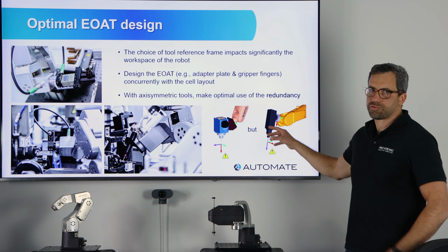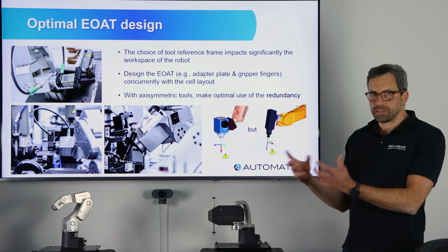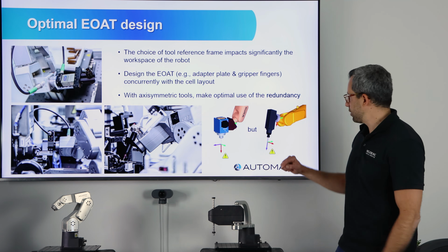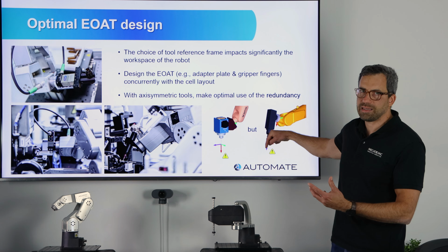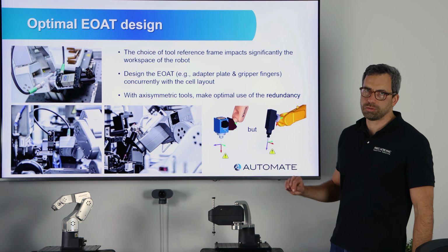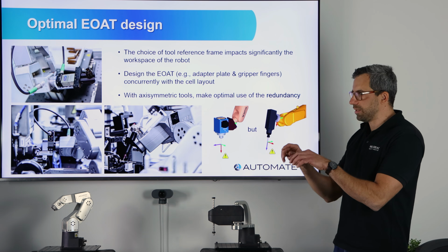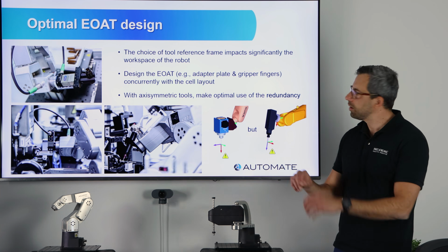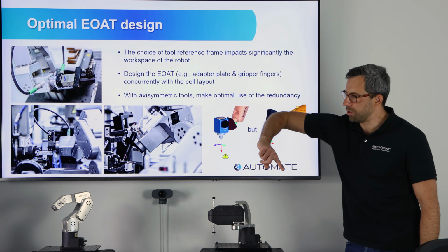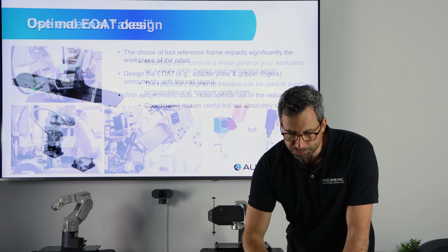In the case of Staubli robots and Mecademic robots, we use a different Euler angle convention where the final rotation is about the z-axis. So you place the z-axis along the axis of the tool, and then just by changing the gamma angle, you can easily obtain a different configuration, which is maybe away from a singularity. So this is something very useful to know.